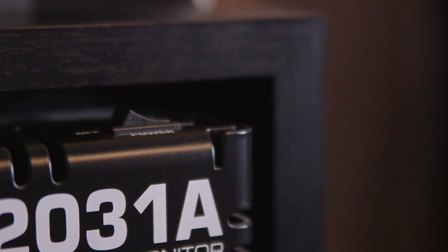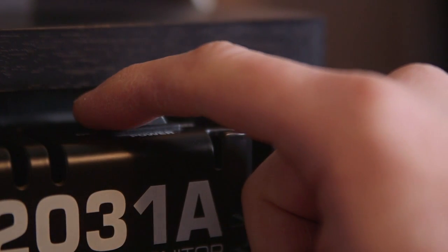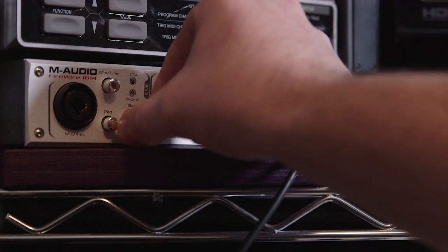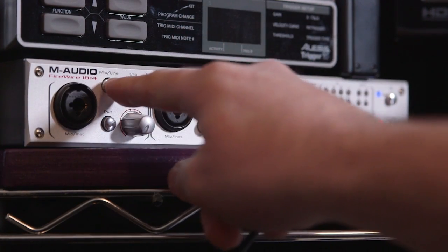Again, before you plug in your microphone to your interface, make sure your speakers or any other amplifiers are off so that you don't cause a feedback loop. I like to turn the microphone gain all the way down as well just to be extra safe. When I first got into recording and audio gear, I left the amplifier on and flipped an input switch on a mixer. The studio monitors went into instant hardware feedback and the tweeters blew. I will never forget that, as it scared me so bad I could hear my own heartbeat.